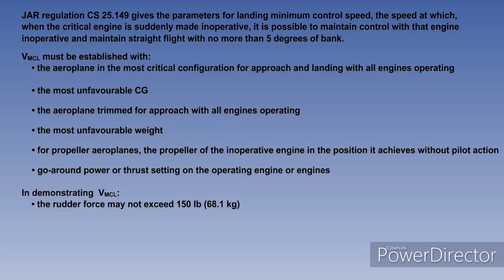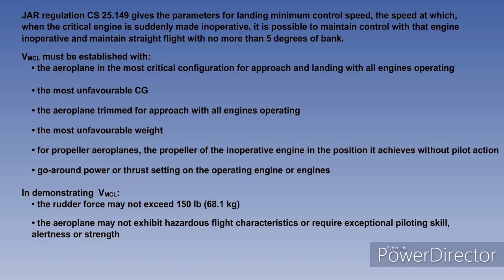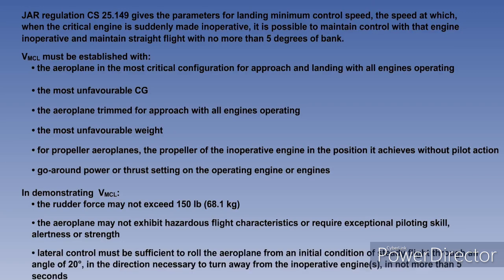In demonstrating VMCL, the rudder force may not exceed 150 pounds. The aeroplane may not exhibit hazardous flight characteristics or require exceptional piloting skill, alertness or strength, and lateral control must be sufficient to roll the aeroplane from an initial condition of steady flight through an angle of 20 degrees in the direction necessary to turn away from the inoperative engine or engines in not more than 5 seconds.